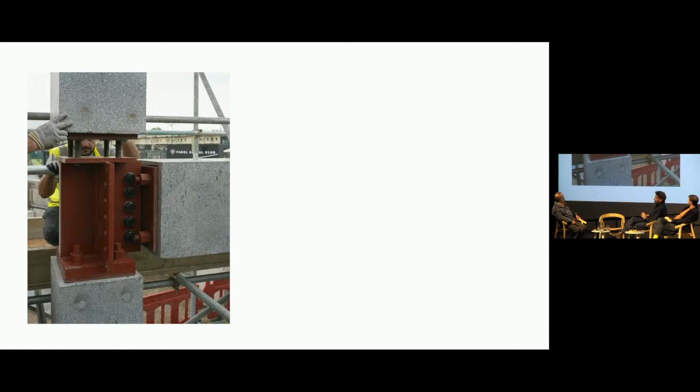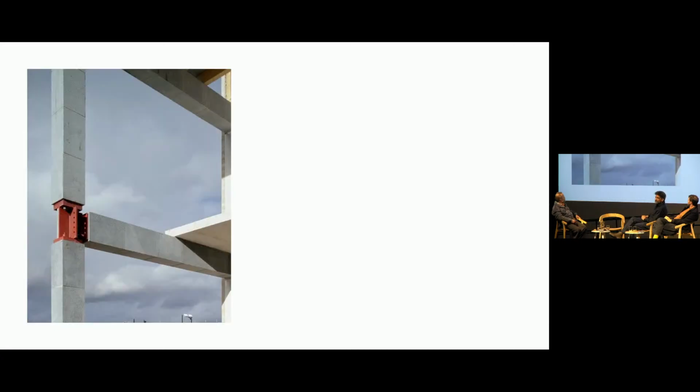The Design Museum has government funding for what's called green transition. How can we green transition all design and construction? So they paid for a decorator that allowed this to be fabricated at Earl's Court. And we made a simple column and beam frame that replaces the equivalent of a concrete frame for residential or commercial buildings, with steel end plates. So the whole thing could be prefabricated, lifted into place, and connected by standard contractors, as if they were putting a steel frame together.